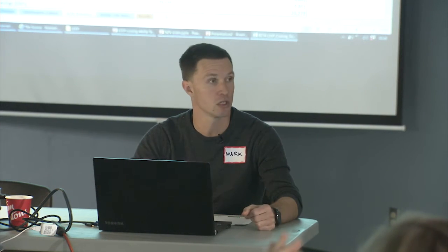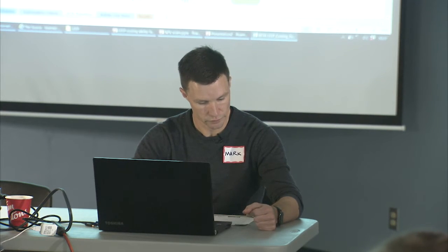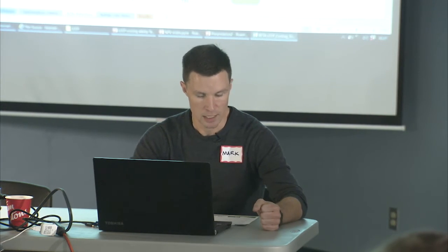So the first thing we're going to try is to get to net zero without giving it the option to use a heat pump as the heating source. So in our ECM table, let's scroll down to the HVAC systems, and let's say no to the cold climate air source heat pump and to the air source heat pump. Now, without changing anything else, let's just click run and we'll see if it spits out a solution for us.